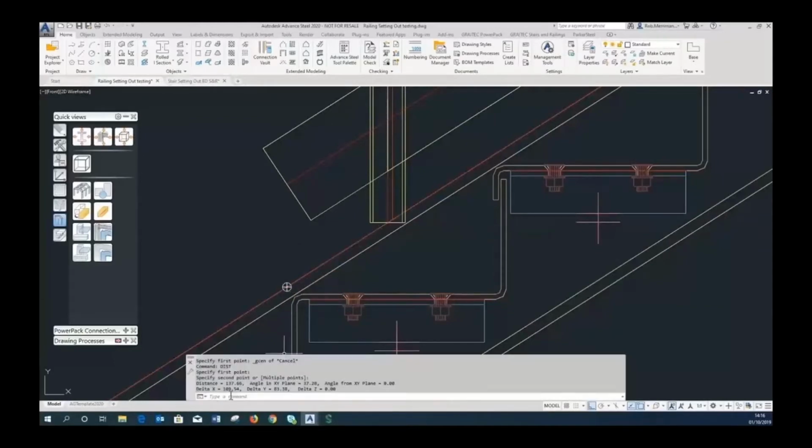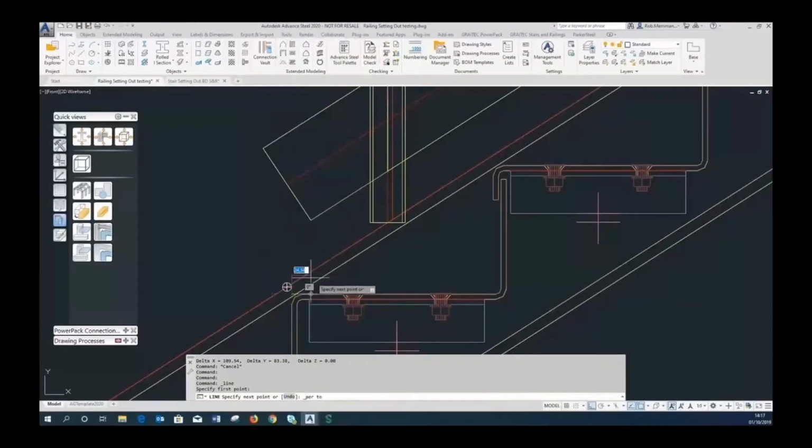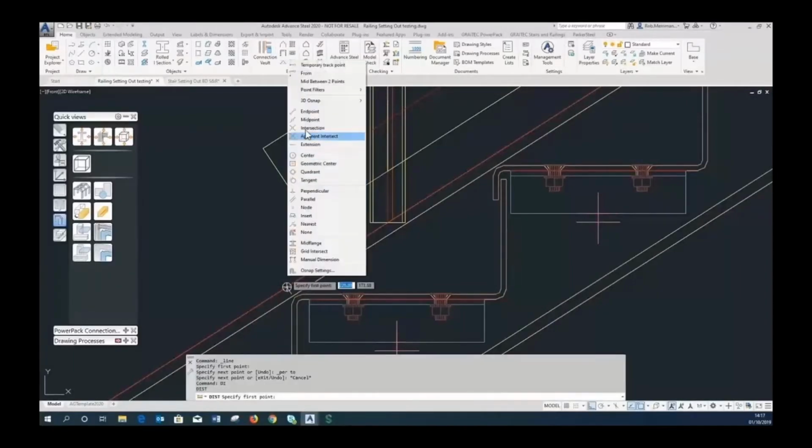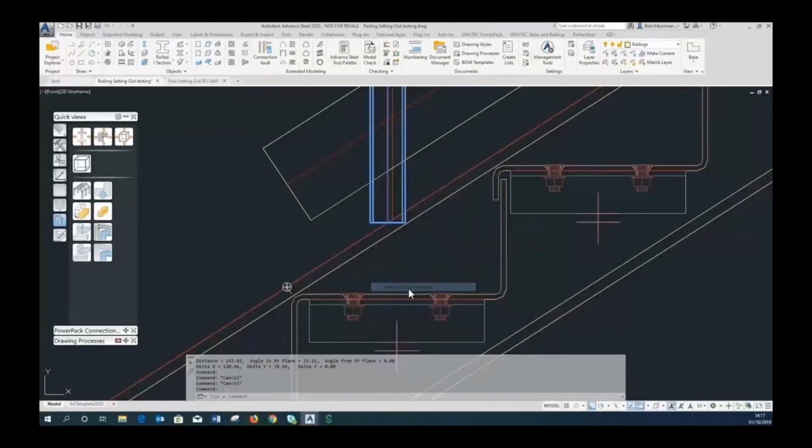So I'm just going to measure what the distance is that I want. You see it's measuring 109 at the moment. I want to do 115. But that's because that start point is not directly above it. The start point is projected perpendicular. So I need to measure from the start point. There you go. You can see how it's been projected perpendicular to the actual point I chose. So I need to measure from that start point to the line I wanted, and its actual distance is 120 there. So I'm going to go back into the joint now.